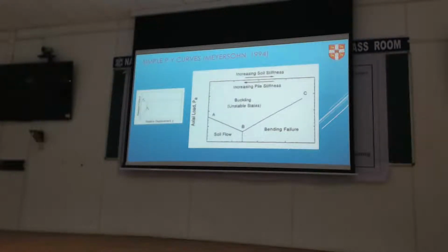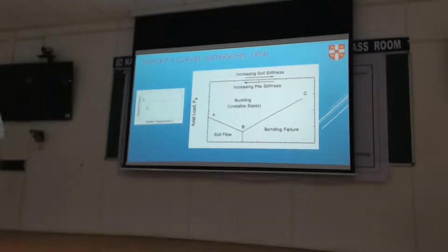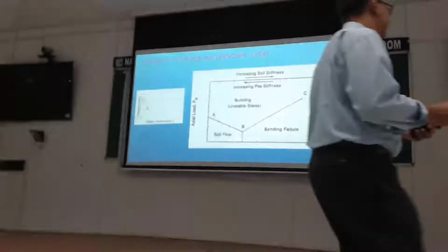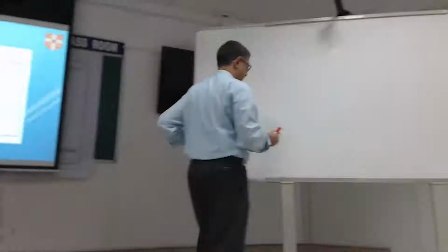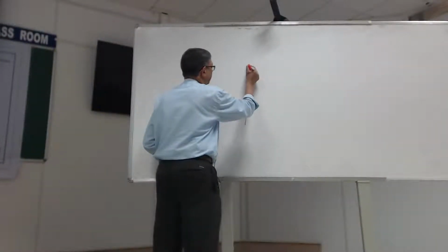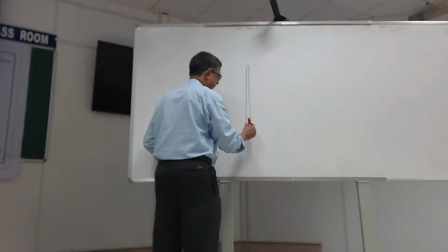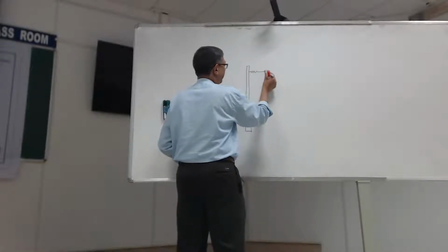We talked a little bit about the PY analysis yesterday of how you can have these lateral springs. So if I can remind you, PY analysis basically involves having lots of springs in the horizontal direction.